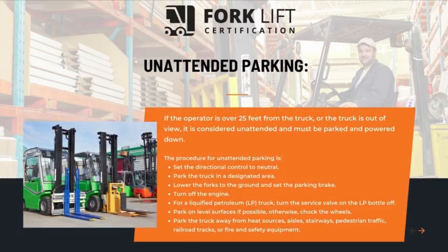Unattended parking. If the operator is over 25 feet from the truck or the truck is out of view, it is considered unattended and must be parked and powered down. The procedure for unattended parking is: set the directional control to neutral, park the truck in a designated area, lower the forks to the ground and set the parking brake, turn off the engine.